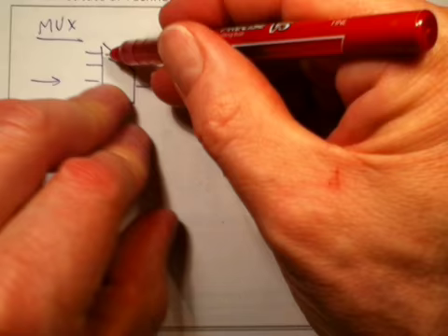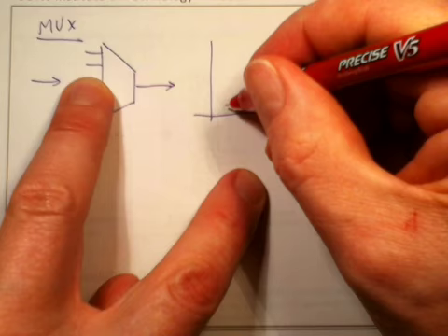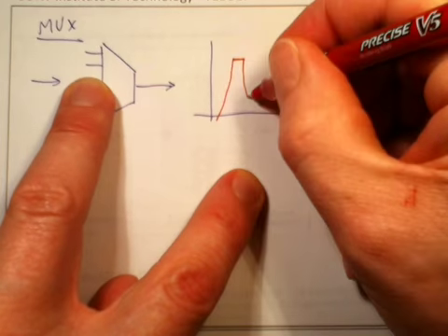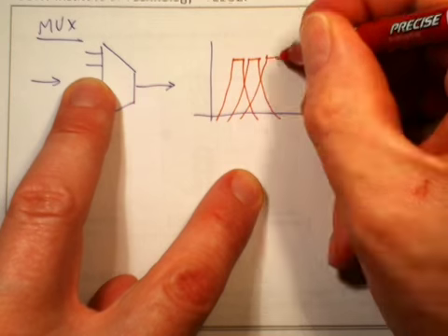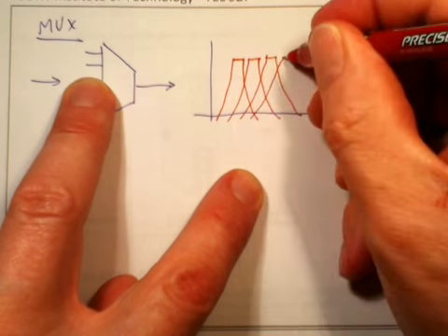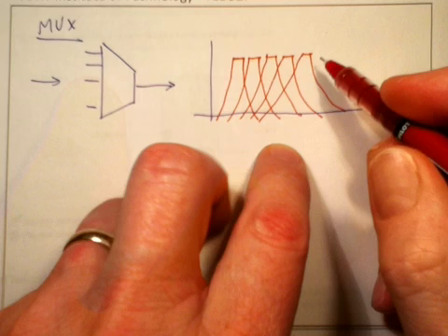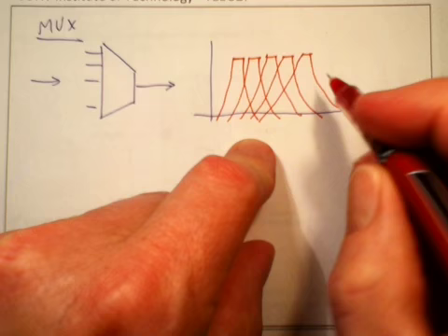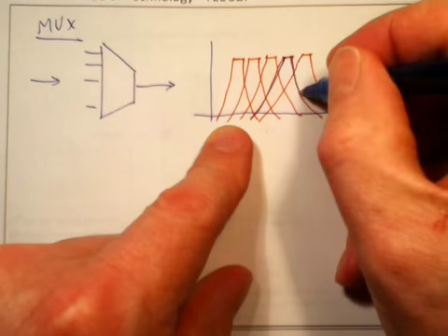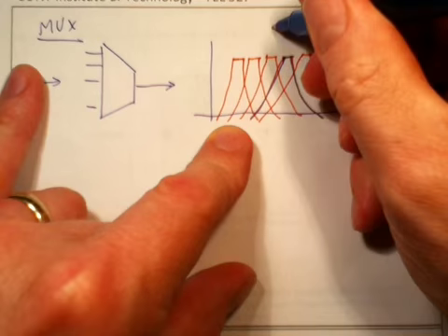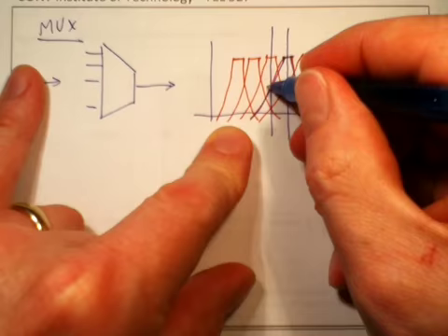Each channel is a bandpass filter, essentially. So we want those channels to be very flat at the top, and this is on a decibel scale for what they look like. We want them to be flat at the top, and we're not so worried about whether or not there's a lot of crosstalk from one channel to the other. So for example, this channel, by the time you get to the center of this adjacent channel, this one doesn't have to be so far down, okay?